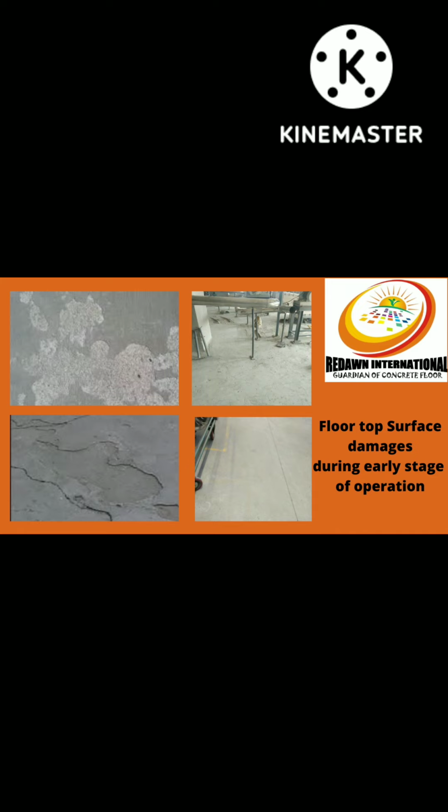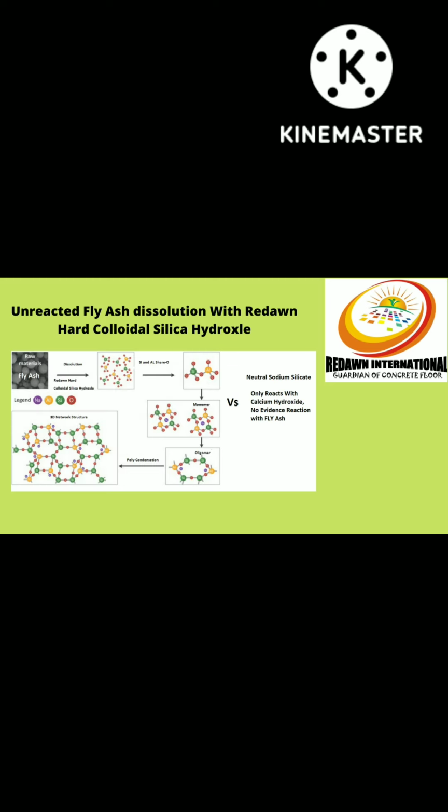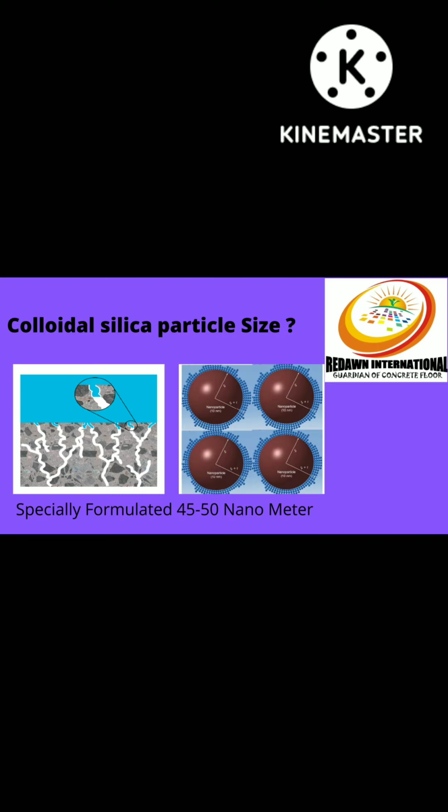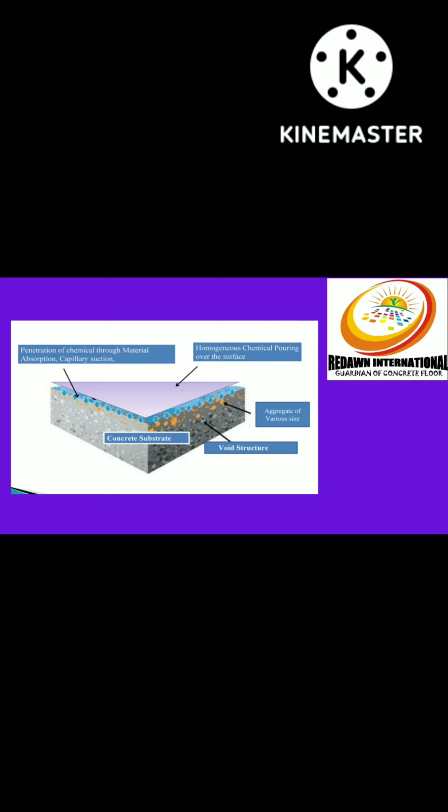Cement paste is not a crystal to begin with. Crystals are molecules stacked together in a regular, repeated pattern. In contrast, calcium silicate hydrate is technically a gel. The molecules are packed together and hard, but they do not form a regular, repeated pattern. The major differences between the products come from particle size, absorption and the sorptivity network made during the reaction process.